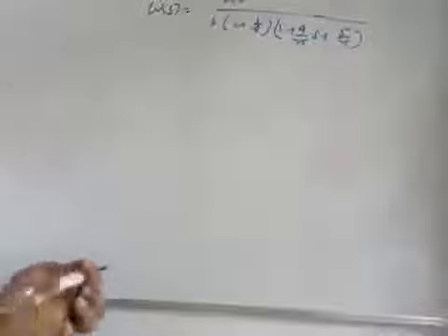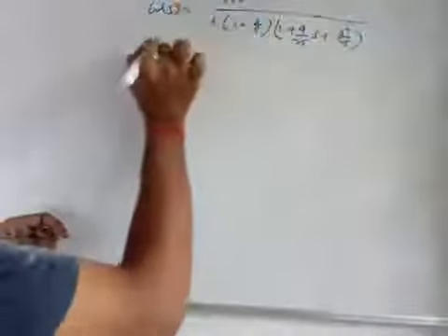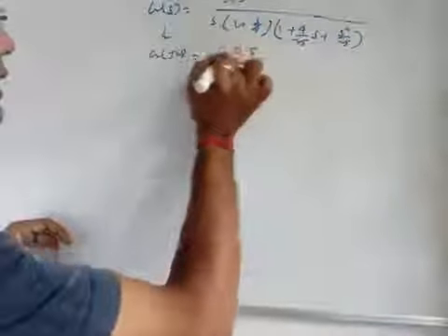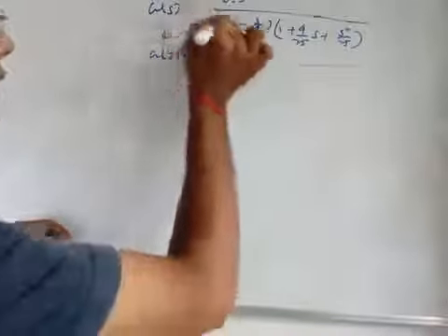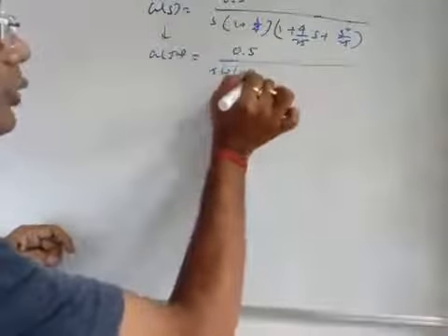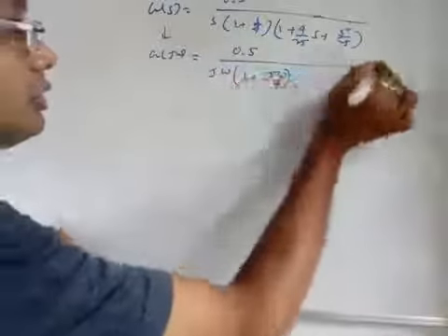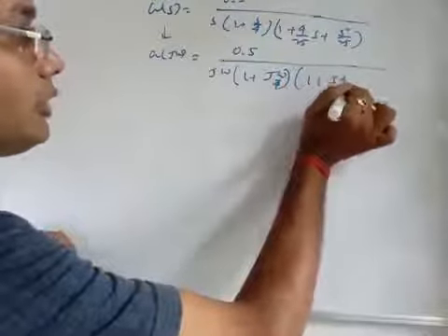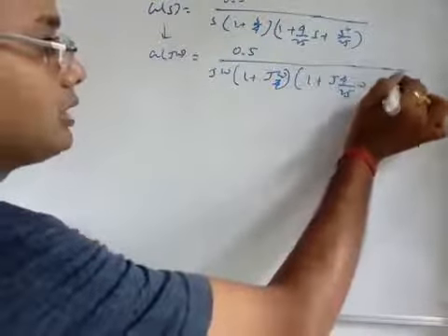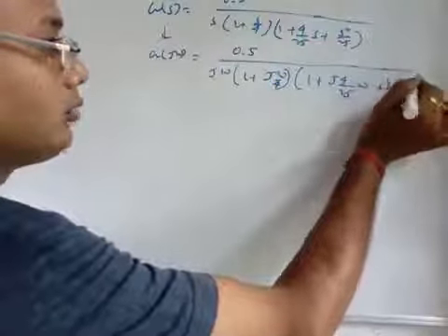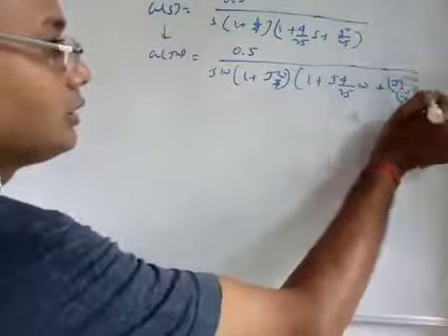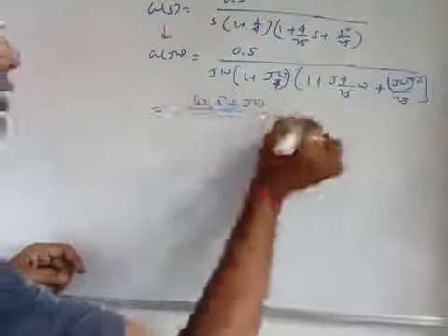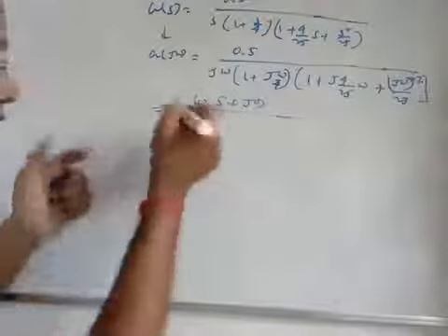So we get the 1 plus st form like this. The next step is to get G(j omega), that is the sinusoidal transfer function. That is as simple as that. Just put the value of s equal to j omega, and you see 1 plus j omega by 4, 1 plus j 4 by 25 omega plus j omega square by 25, right? So this is 0 plus j0, we can write like this to get the magnitude part very easily.